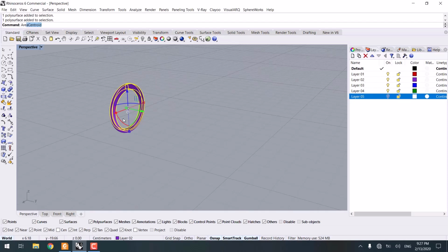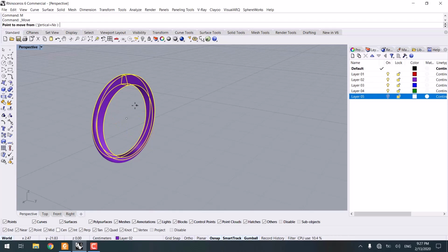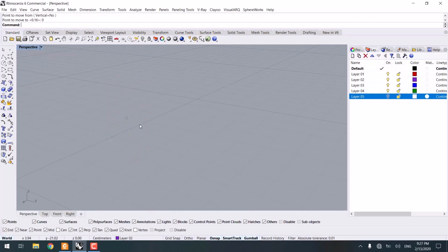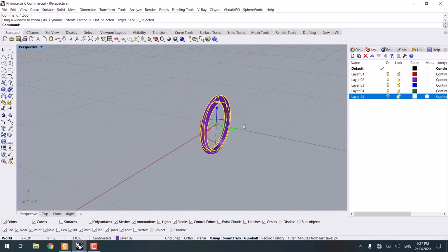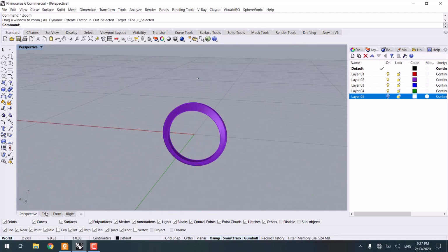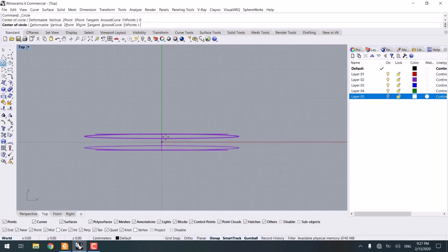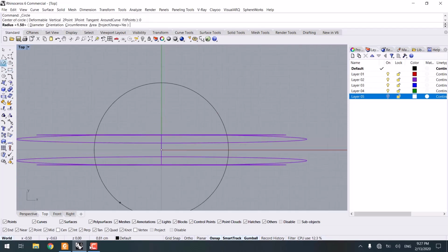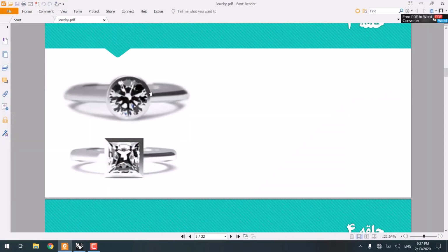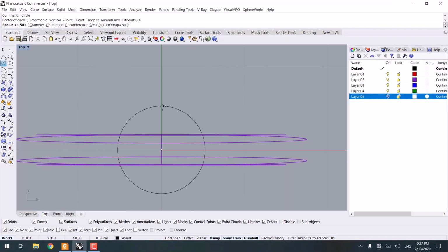Now, I'm going to use area centroid to specify the center point, and then use the center point to move the circle to the 0 and 0 coordinates. Then afterwards, I'm going to change up my view to the top view more precisely, and try setting a circle here with a specific radius, based on what we have in the image.